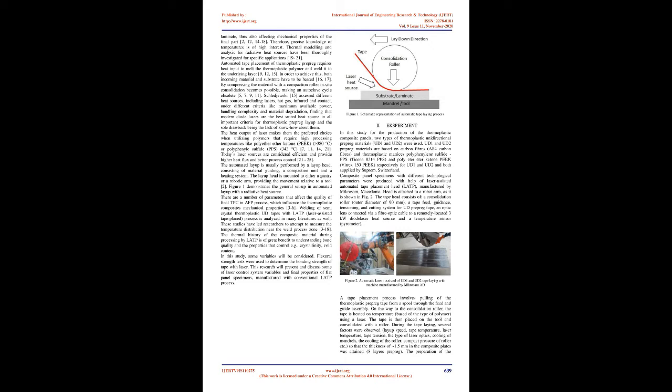The heat output of lasers makes them the preferred choice when utilizing polymers that require high processing temperatures, like polyether ether ketone, PEEK, greater than 380 degrees C, or polyphenylene sulfide, PPS, 343 degrees Celsius [7, 11, 14, 21]. Today's laser sources are considered efficient and provide higher heat flux and better process control.